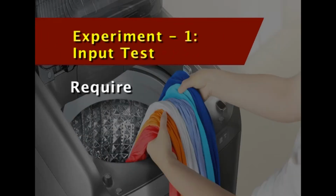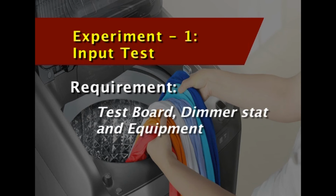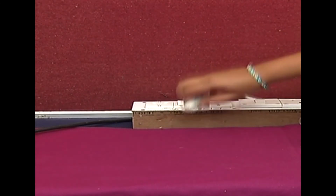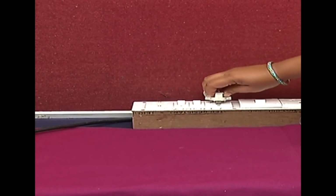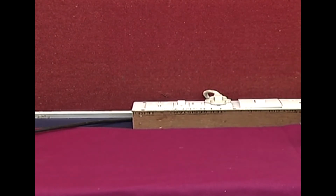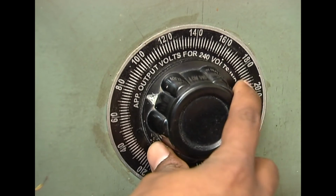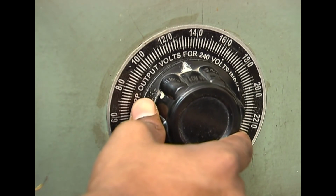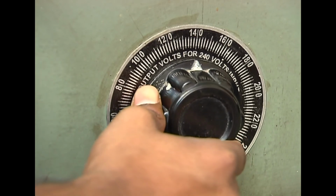The materials required are test board, dimmer stat and equipment. The procedure: the 3-pin plug, the equipment is connected to the socket depending upon the wattage of the equipment. Switch on the supply. Rotate the dimmer stat till the voltmeter reads 230 volts or the voltage marked on the nameplate of the equipment. After approximately 5 minutes, note down the ammeter and wattmeter reading.